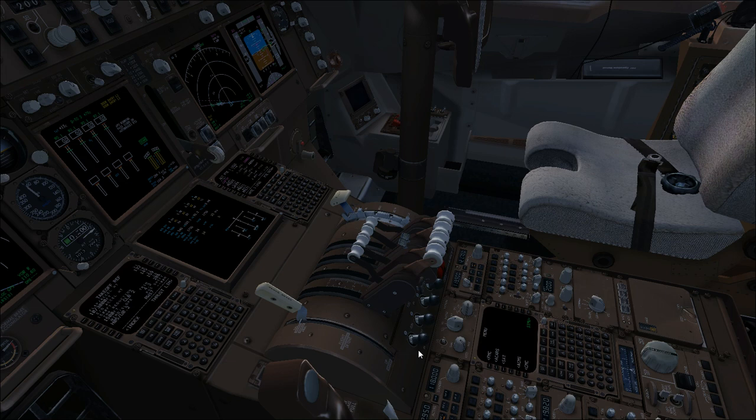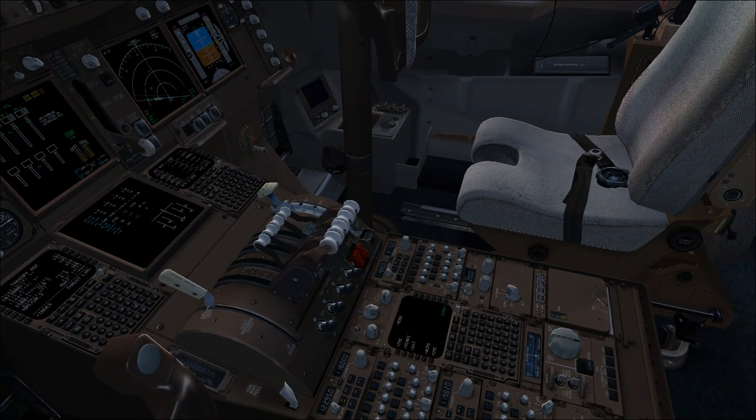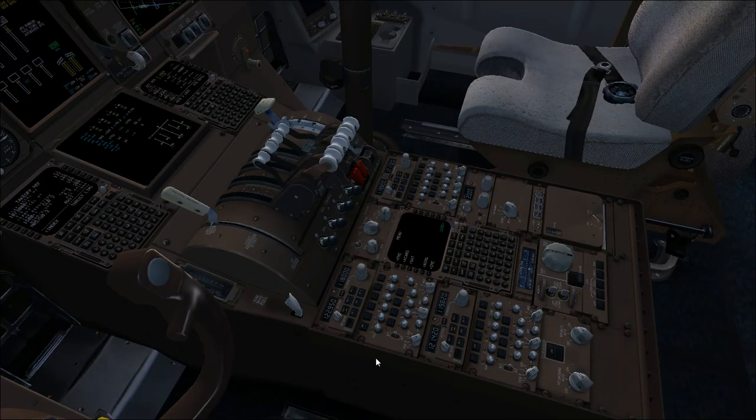Fuel control switch warning lights are off. There are red lights inside the caps of the switches. You can check it, that is off. Then you can move to stabilizer trim cutout switch, guard closed. Alternate stabilizer trim switches to neutral. Captain CDU control panel is set, and pre-flight checklist must be called now.